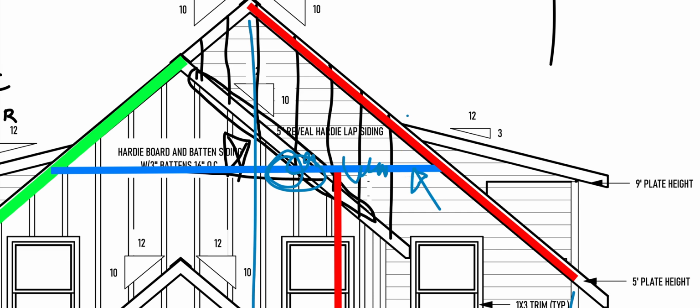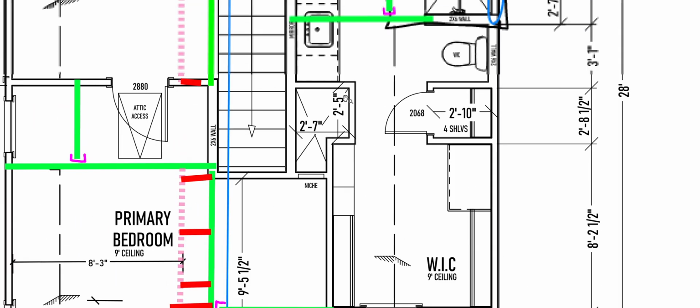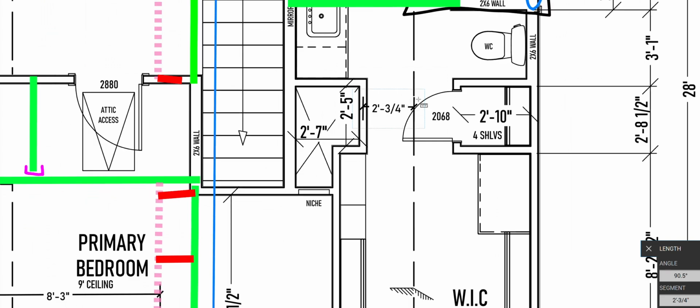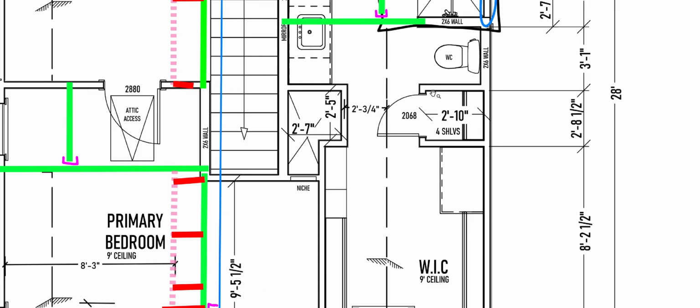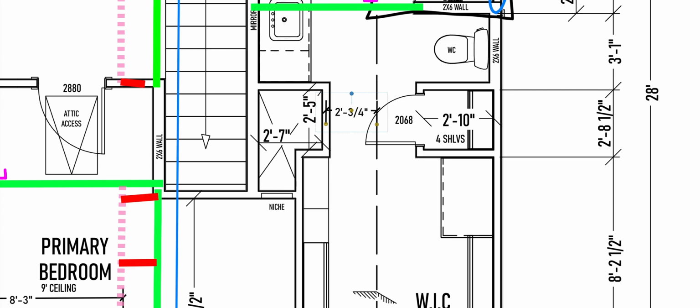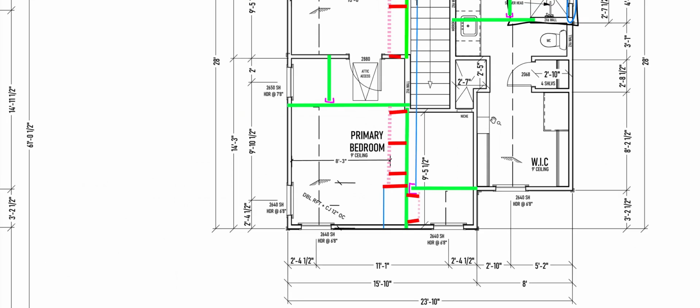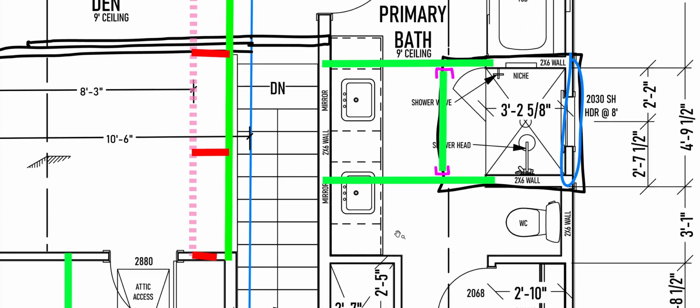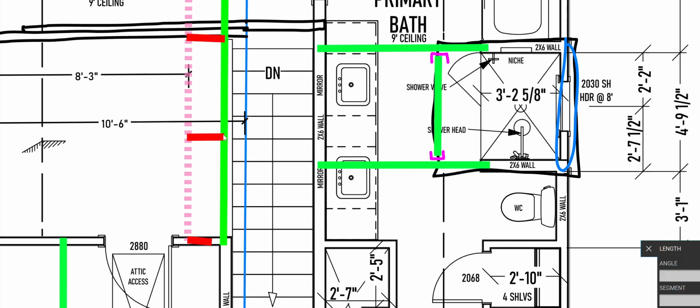be almost nothing. So I'm going to go back to my floor plan and look at the real spacing of things. And I'm going to see that right here, it's even better, right? So I've got ceiling sitting on this, tying into this, which means I only have approximately 2 feet of ceiling sitting on my rafter. So that's going to basically not affect my rafter at all. And then on the worst case scenario, which is in the bathroom, this is probably about 3 feet of ceiling, and this is probably like 5 feet, 4 feet, something like that. Let's get a number on it.